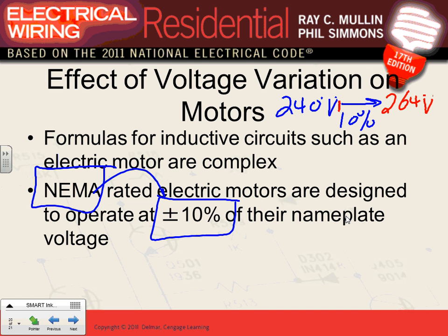Now, by the same token, if I have minus 10%, so this is plus 10%, meaning extra 10% of the voltage. Okay, how do you make a minus 10% on a voltage? Basically, take 10% out of 100%, I'll get 90. So 0.9 times 240, what do you get? Geniuses here? 216. 216 volt. So what this tells you is the appliances are supposed to function properly between this voltage and this voltage. Now, Kerry, why do you think this is very important?